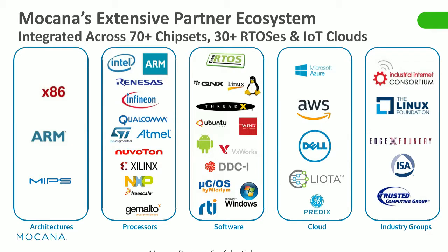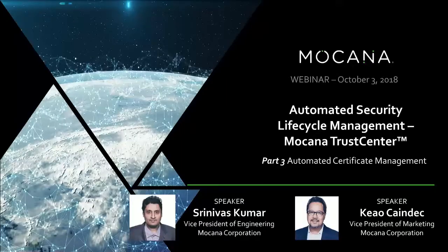We also provide enhanced secure boot, which is called cyber boot, where we integrate with the first stage bootloader. We do it in a way that we can support UEFI boot as well as flash-based boot. And that basically hardens the device from power on and then allows us to do the device fingerprinting to provide, like someone just asked, flash-based protection. So it's a cascade effect of making sure the boot was verifiable.